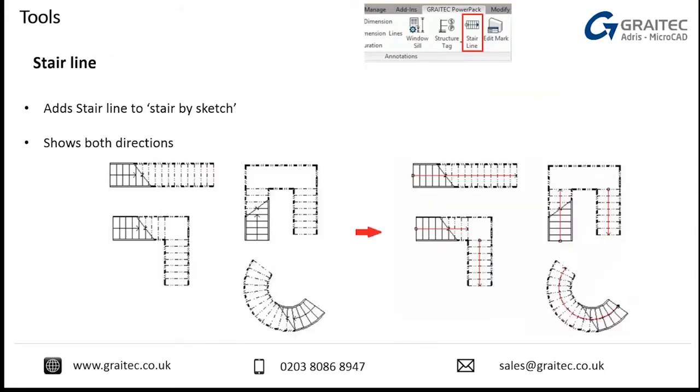We've got a stair line, and again, this is something that's been requested by users. By default Revit will only draw the stair line up to where the split is. So depending on your view range is where the split line goes. You can see on the left-hand side there, the line only goes 4 stairs, 4 rises, whereas we've got a tool now that will put the whole run in. It will put a line in from the bottom to the top with the direction listed as well.